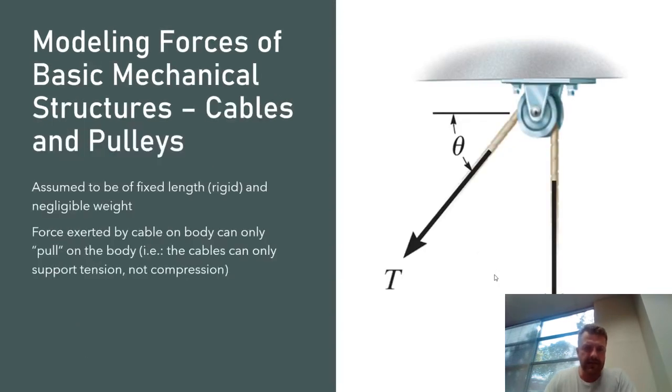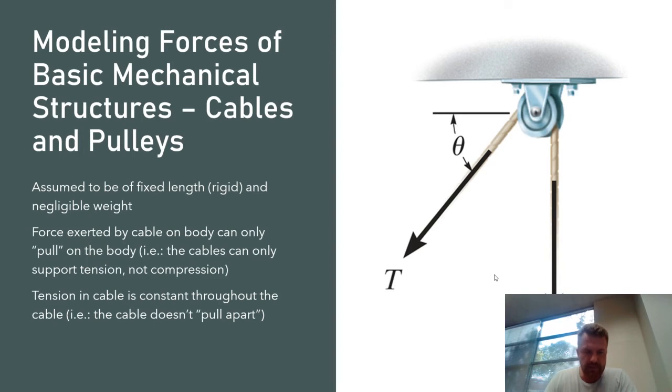not the total length of the spring. So what about forces actually exerted by cables? We're always going to assume that our cables are fixed length, meaning that they can't stretch or compress, and that they are of negligible weight. In addition, we're going to assume that when a cable exerts a force on a body, it can only pull on the body. What that means is it can only support tension and not compression.